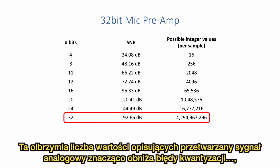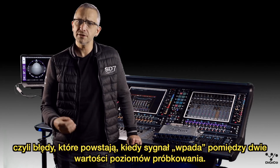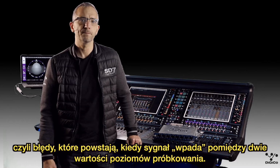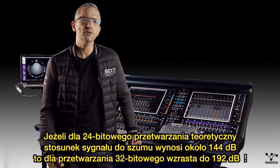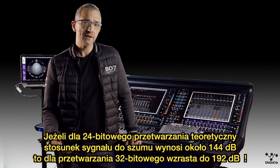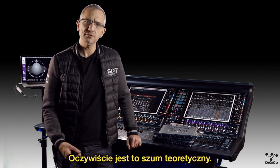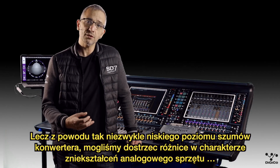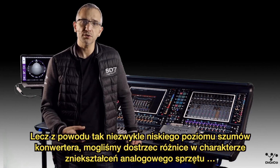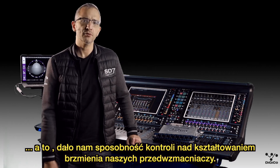This massive increase in digital values to represent the incoming analog signal means the quantization errors, that's the errors which result in noise when the signal falls between two digital values, is significantly reduced. So while a 24-bit conversion has a theoretical signal-to-noise ratio of about 144 dB, at 32 bits, this signal-to-noise ratio increases to 192 dB. Of course, this is theoretical noise, but because of the amazingly low converter noise, the real-life analog noise floor becomes much more about the component choices in our circuits, and this gave us the opportunity to control the shaping of the sound of our preamps.